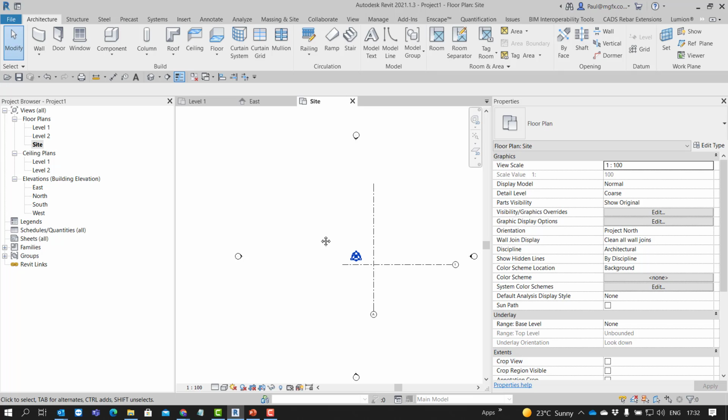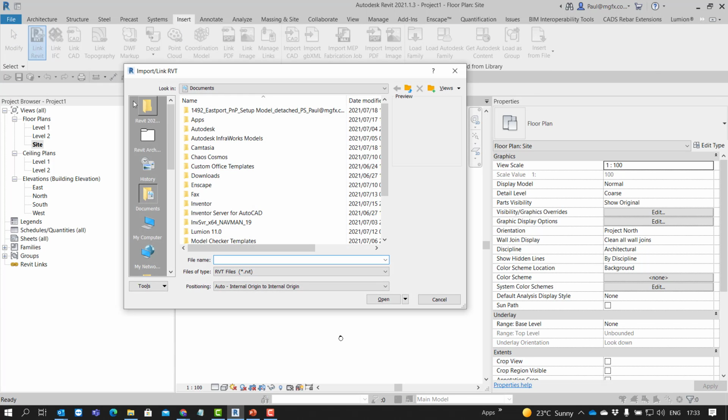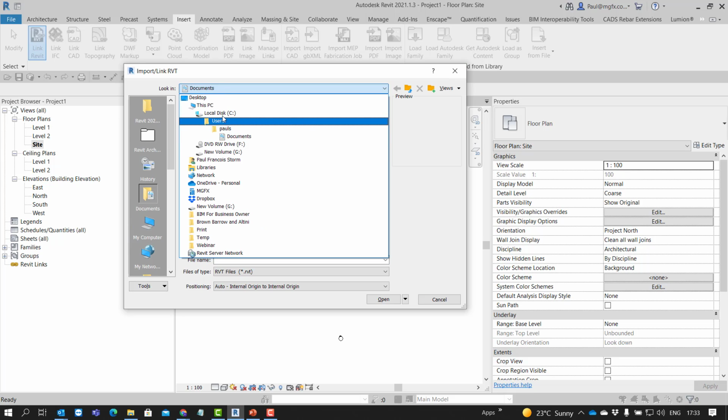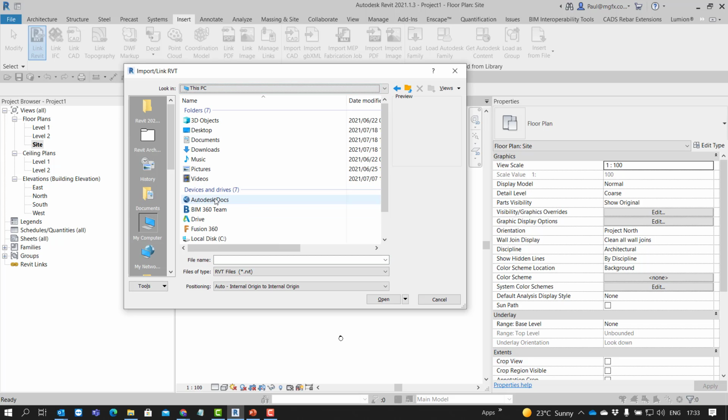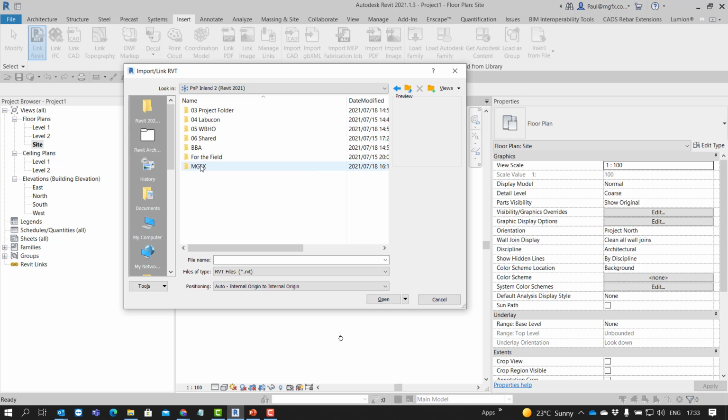And then we're going to bring in the linked file. Now currently, if you go to the Revit links, you'll see that it doesn't give you the cloud option. So you do have access to this file if you look in your PC. When your desktop connector synchronizes down onto your computer, in this case you'll see that it only shows me the folders that I've got. Over there is my company folder, the MJFX folder, and there's the consumed folder, and there's the ICM folder. Those are the Revit files that I've got access to.